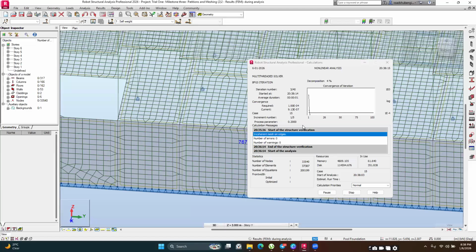The type of errors that I would recommend you have another look at your model or redo your work is if you're having the instability errors. If you're having errors in instability type 1, instability type 2, instability type 3, those ones will need you to give more care to them so that you ensure that your structure is okay and it is safe to stand, if I may use that.